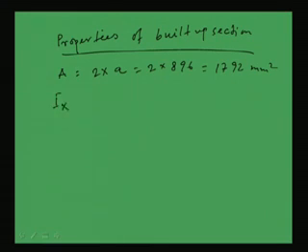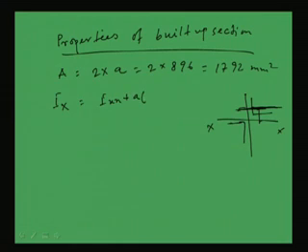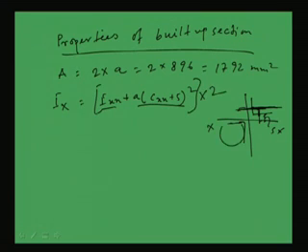Similarly, we can find out the IX. If we see, say one is given here, another is given here, right. Now IX will be simply IXX about this, then A R square. So, that will be IXX plus A into R square. R square means this is 5 millimeter and this is CYY or CXX. That means this will be Cxx plus 5 millimeter. So IXX plus A R square, and into 2, because 2 members are there, here one member, another member here. So Ix will be this. As these are symmetric, Ix will be totally this into 2.